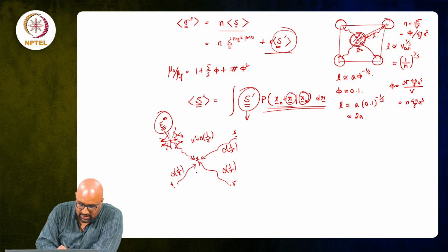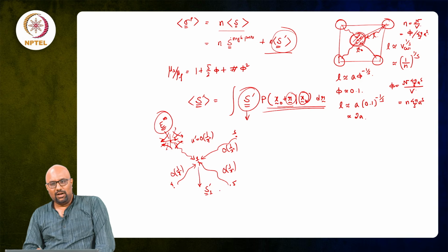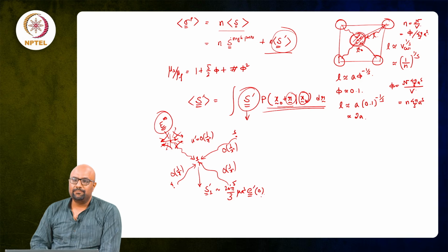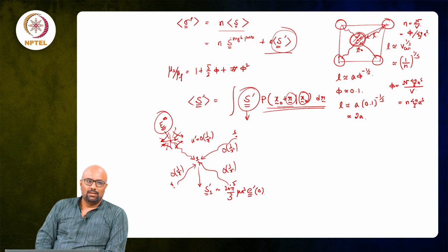Now, the question is, what is the stresslet that is created for sphere 1 due to these 1 over r square velocity fields? That should be 20 pi by 3 mu a cube and E perturbation at sphere 1, right.